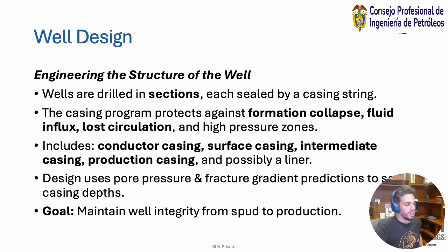You need to drill incrementally. First of all, these drill bits get really hot and they get damaged, believe it or not, after all this usage, and you don't want to get stuck down there. So you want to be incrementally drilling, stopping, cleaning. It's this circular, iterative process, and then you're choosing the direction and all these different things. So when we say drilling, we're talking about rate of penetration, horsepower, and torque, but we also need to consider cleaning, and we need to consider not to get any kicks.